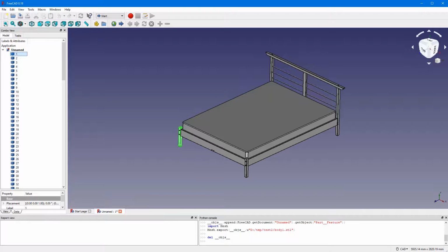Just a side note, there might be separate volumes in your model that you can handle together. For example, there are 50 slats in this model. If we don't want to access the individual slats separately, only together, and they will have the same color and the same displacement vectors, then we can make a single STL file from these 50 volumes. In all subscription packages, the number of files are also limited. In this way, you can reduce them without sacrificing quality.